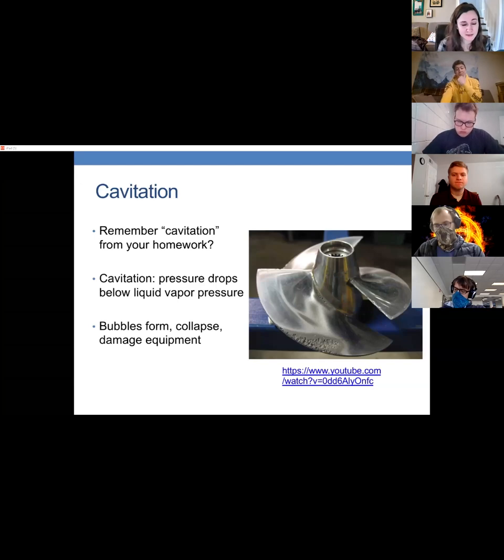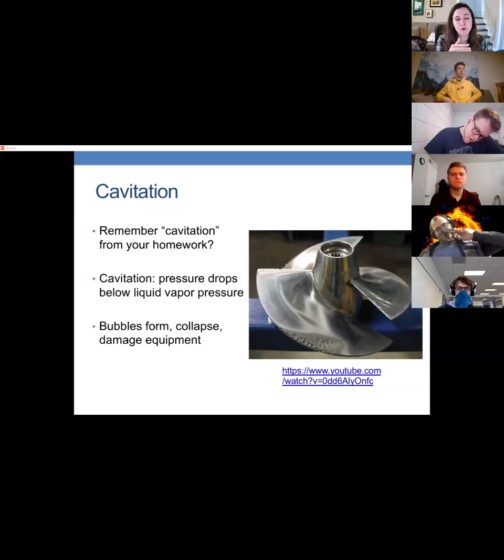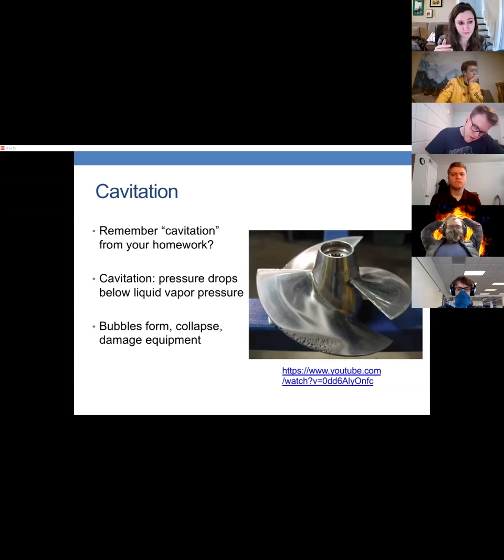So a couple other things just to note from what he said. He said that when you go through a partially closed valve, the pressure drops. Does that make sense to us? All right, that's part of what minor losses are about. Specifically, he said the pressure will drop over the partially closed valve, and then it will come back up again afterwards. It will come back up again, but it won't come back all the way to what it was before. That is what will happen over a valve like that. Okay.